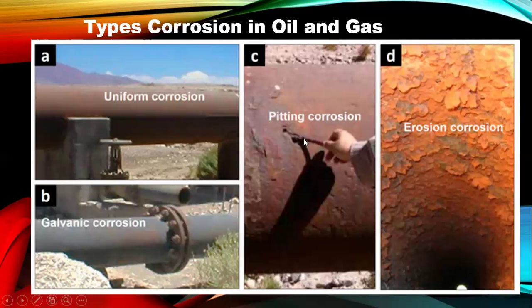And then corrosion due to stress. Now, if there's any stress on a pipe, oxygen tends to attach to that area and then start corroding. So these are various corrosion types, but I think what we are trying to prevent here is mainly pitting and also erosion. Erosion is one of the most critical ones that has to be prevented, especially inside the pipe. Now, a region like just after your wellhead, going down after your Christmas tree, going down to your choke manifold, your choke.